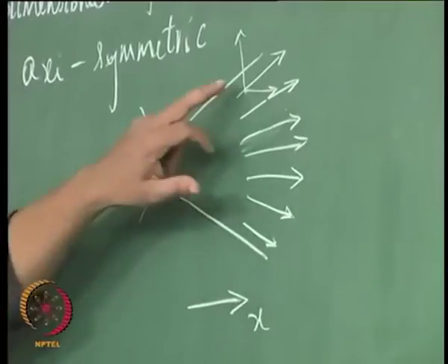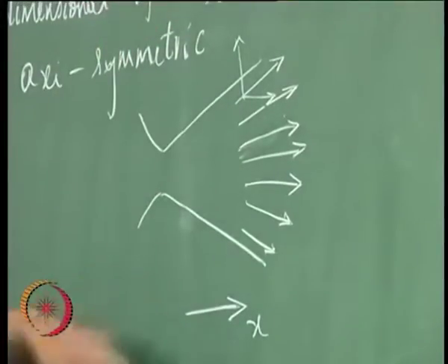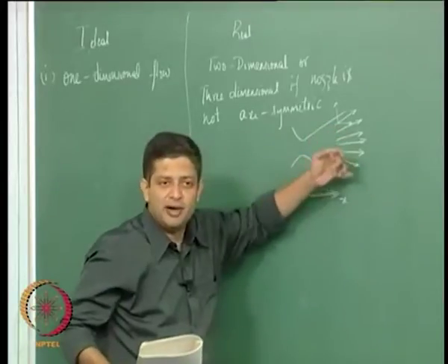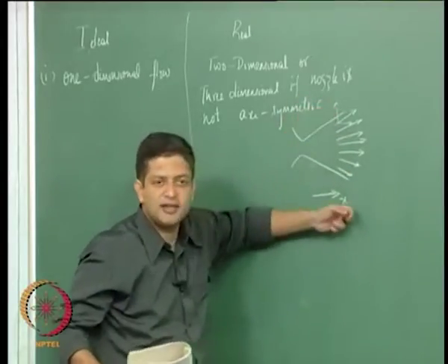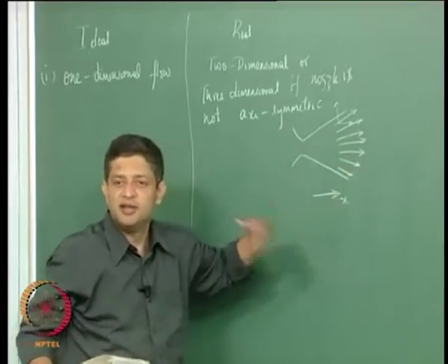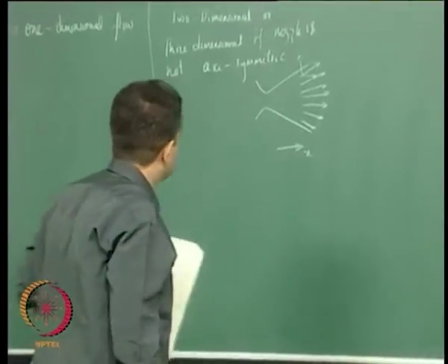There is going to be a component that is going to go wasted. If it is axisymmetric, they will cancel each other out because of symmetry, right. So, there is only one component of this in the x direction that we need to consider, but we had considered the whole thing to be the exit velocity. So, that will lead to something known as divergence loss.